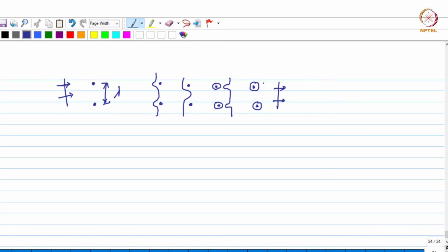Okay, so due to these loops, the dislocations which are coming after this will find it difficult to move through these particles. Okay, so that will contribute to some hardening in this case, but ultimately, since we are aging this material now for a prolonged period beyond the peak aging time, the distance between the particles will increase because the particles will grow, right? So this lambda is going to increase. So that is the other effect that we are going to see at this particular stage of the precipitation hardening. Particles will grow and lambda will increase.